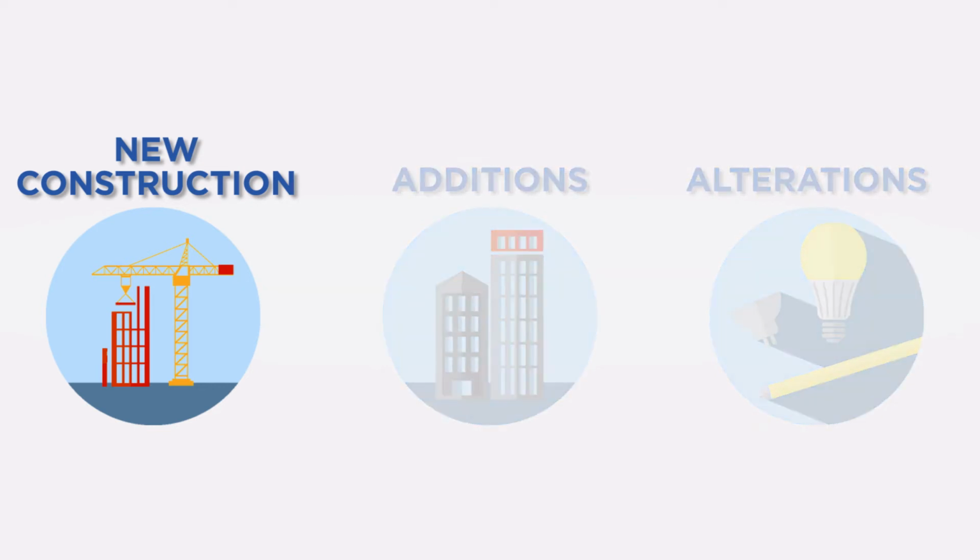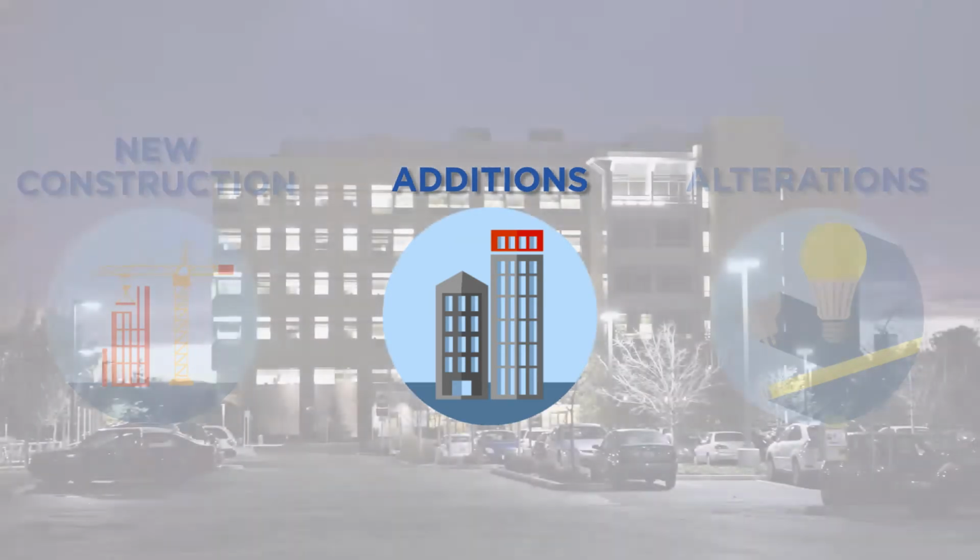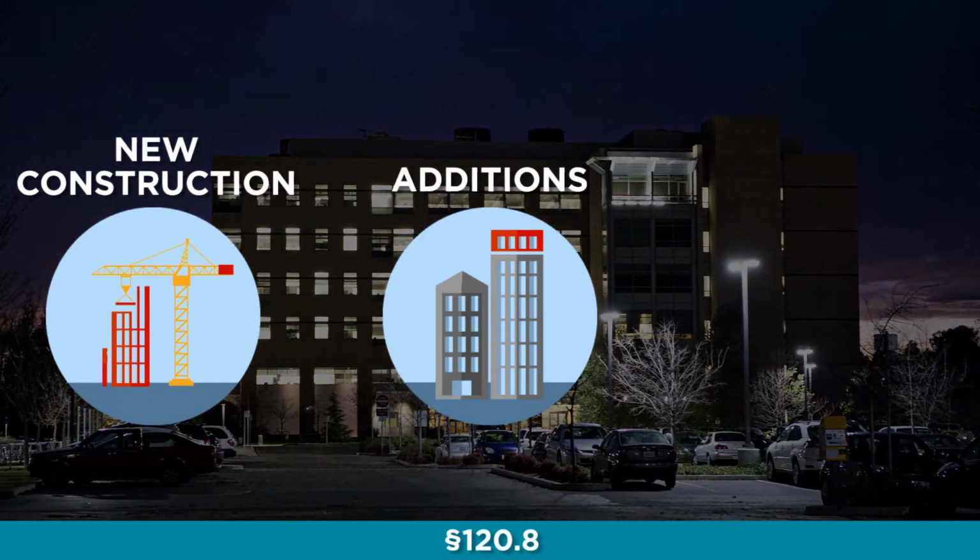New construction refers to construction of entirely new structures. Additions are any changes to a building that increase floor area and volume of the building. Additions are also any changes that increase the illuminated area of an outdoor lighting application regulated by the standards. For both newly constructed buildings and additions, testing is required for any size project. For buildings 10,000 square feet or greater, test results must be included in commissioning documents.